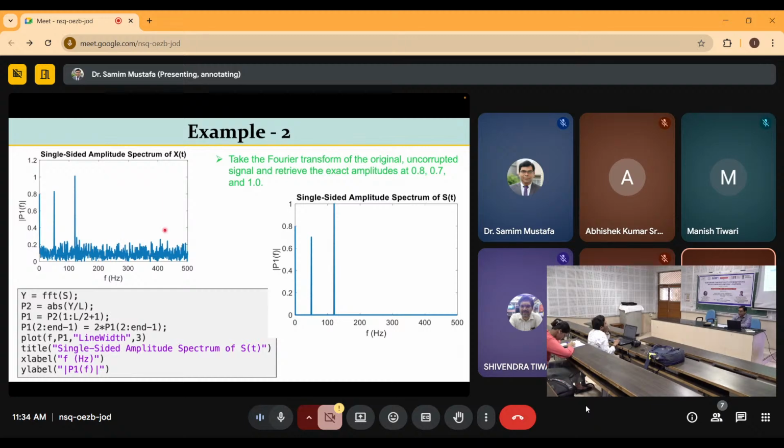So the frequency spectrum will reveal the actual contribution coming from the system, because each system has certain dominant frequencies, and at those frequencies you will see certain peaks. For bridge vibration, the bridge has a certain natural frequency. You have heard in physics class, probably class 12, that marching on a bridge is prohibited, because it could create resonance between the marching frequency and the natural frequency of the bridge. So that is the thing.